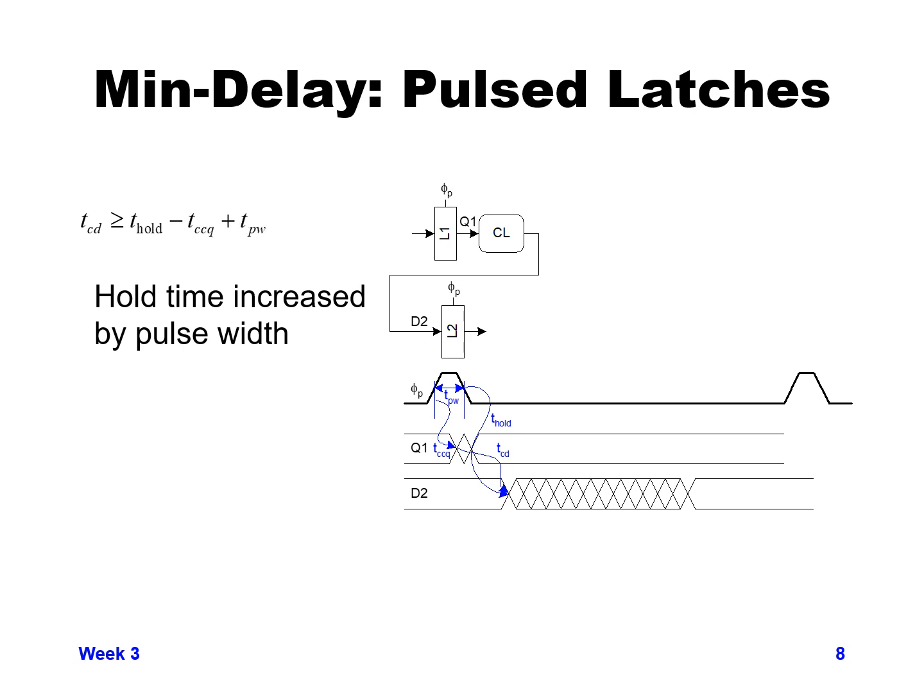In this case, our minimum time for the data going through the combinational logic has to be greater than T sub hold minus our contamination delay time from clock to Q plus the pulse width of the clock. So as your pulse width of your clock gets greater, you have to have more delay time through your combinational logic in order to guarantee that you won't fail this hold time check.